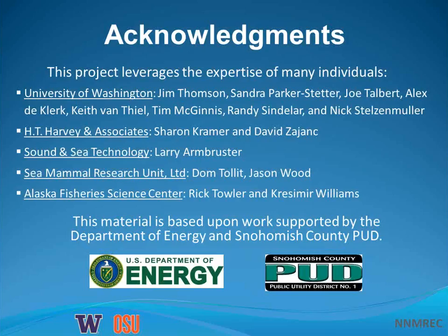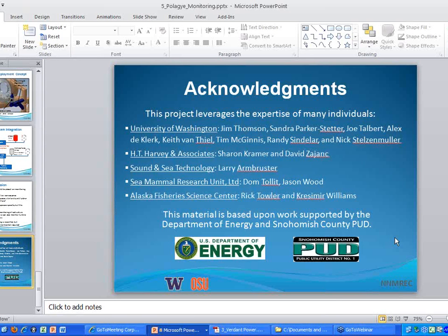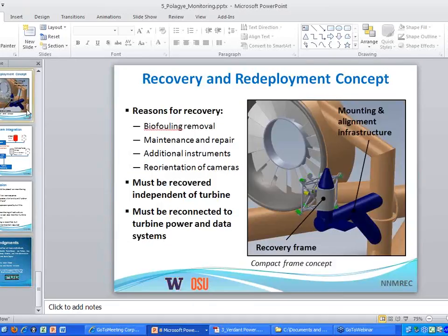Perfect. Second question, for blade strike, did you consider using accelerometers mounted on the blades? There's certainly some consideration to other methods aside from video for detecting blade strike. It's possible that there may be an acoustic signature, in which case the hydrophone array could detect it. One of the issues associated with instrumenting the blades, however, is that if you think about the way the open hydro turbine is designed, getting real-time information off of the blades would require a slip ring of the same diameter as the entire turbine. So for this case, we'd be talking about a 6-meter slip ring, which means instrumentation on the blades, especially for some sort of real-time detection, is rather problematic.